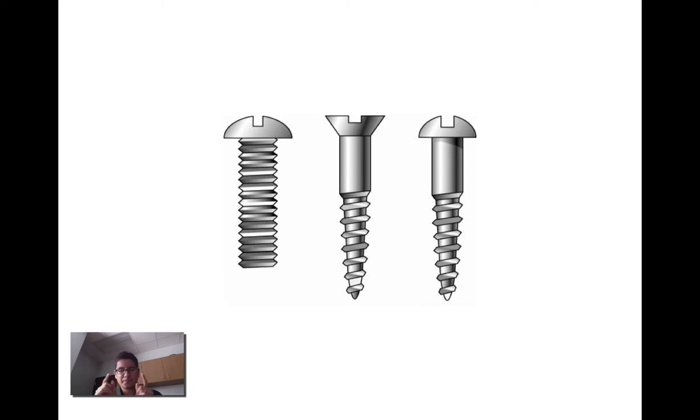That disperses the amount of force that you need to press it down. It disperses the force through an inclined plane. So think of a screw as an inclined plane, because those threads are inclined, there's an angle to them. The more threads you have and the closer they are together, the more mechanical advantage you have, which makes it easier to screw that screw into another surface.